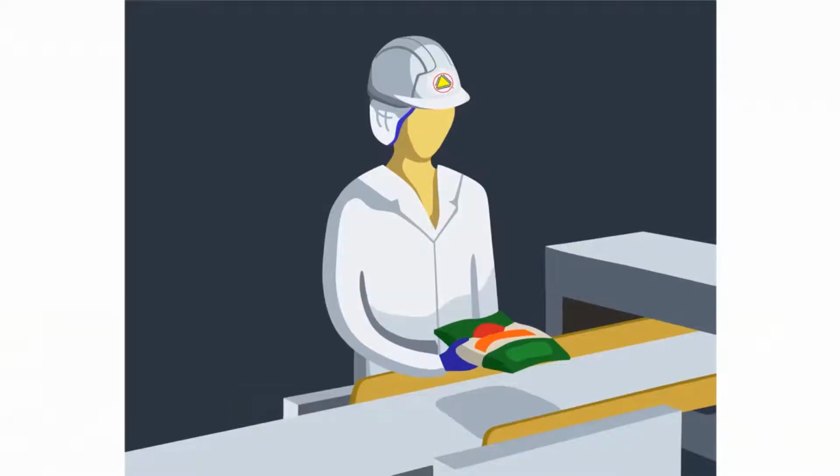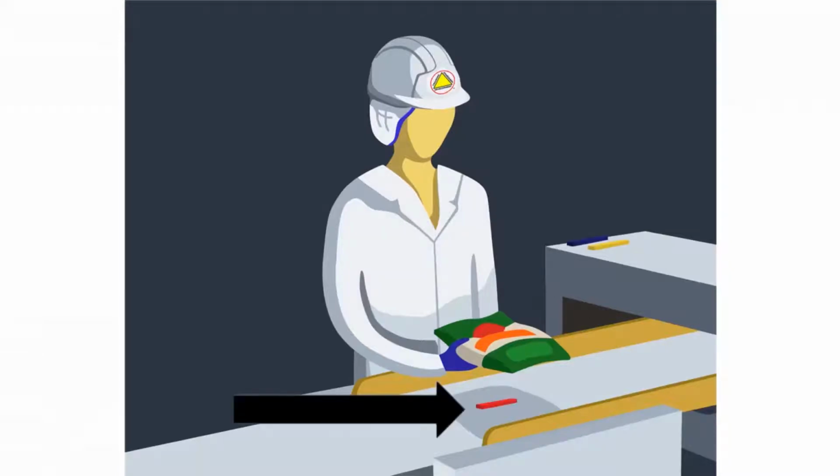Start by passing through a bag with the product without any test strip. The product must pass through the metal detector undetected. Then, we place the red test strip with the product at the geometric center and pass it through the metal detector. Subsequently, we place the blue test strip with the product at the geometric center and pass it through the metal detector. Finally, we place the yellow test strip with the product at the geometric center and perform the same process as above. The metal detector is considered functional if it detects each of the test strips.